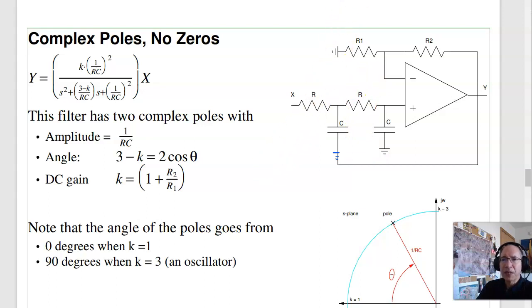Positive feedback is like at a rock concert. If I crank up the volume, the sound goes from the speaker through the air to the microphone to the amplifier and back to the speaker. At a certain frequency, it's going to add in phase. If the gain at that frequency is too big, I get this horrible screeching. That's when you go unstable. That's what I want to do here: add positive feedback to make this go unstable, to make it screech.